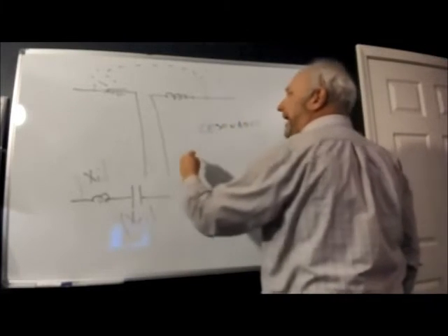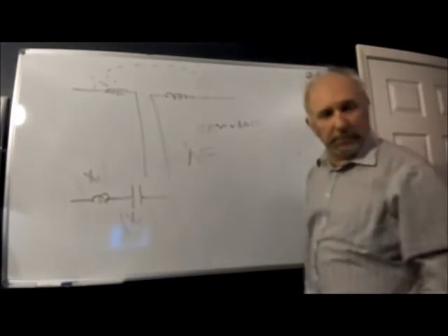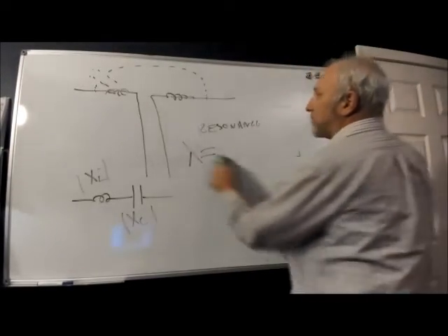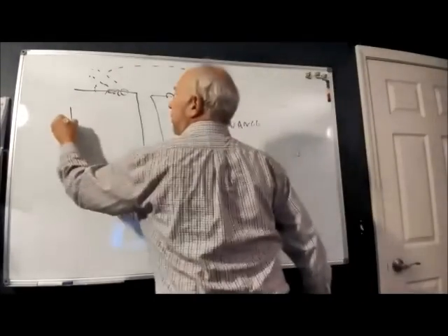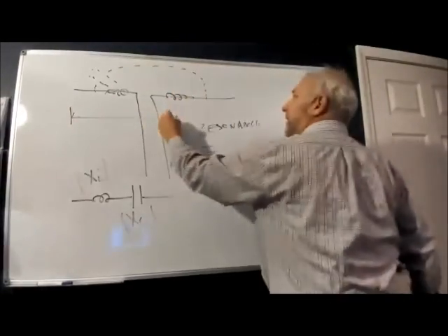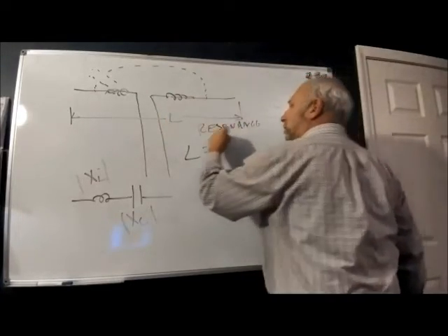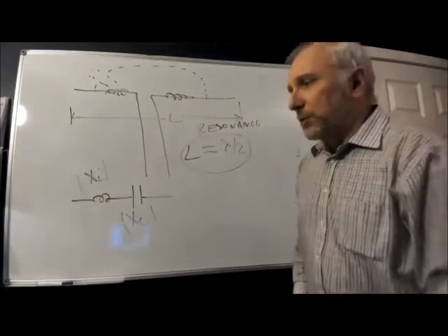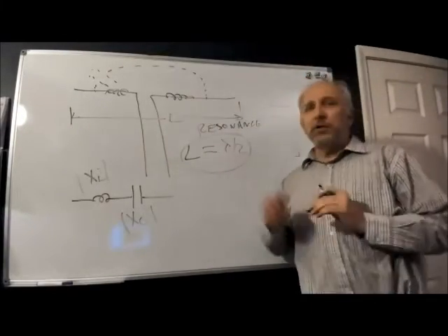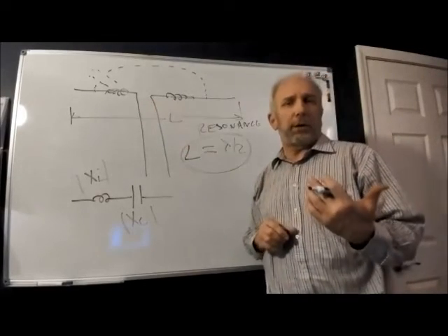And resonance actually occurs at L, the physical length of the dipole antenna. L is equal to lambda over 2. So what's that say? That says all things being equal, as we change the length of our antenna, either intentionally or unintentionally, the resonant frequency will change.